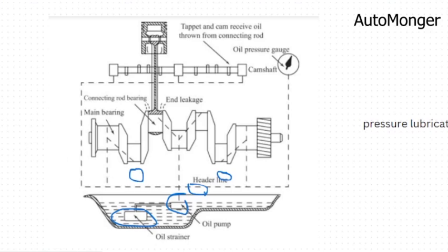The oil pump controls this. The oil pump is equipped to be able to do the whole job that is required. So it has a very high pressure that pumps the oil directly. You can see the direction of oil movement. The oil moves directly to everywhere, to the camshaft and everywhere that is needed. You can see to the main bearing and all the joints everywhere. There are little holes that collect the oil. It is designed to pump oil to all these points. And because it is coming directly from the pump, the pressure is high.